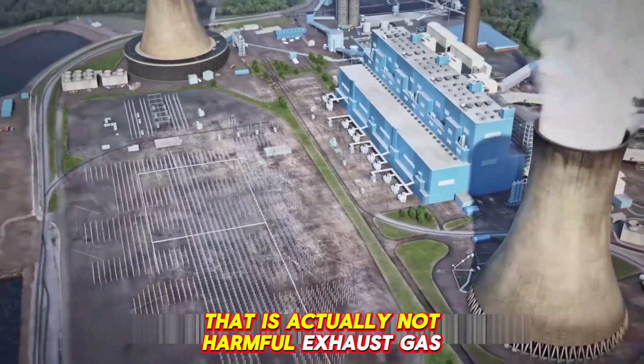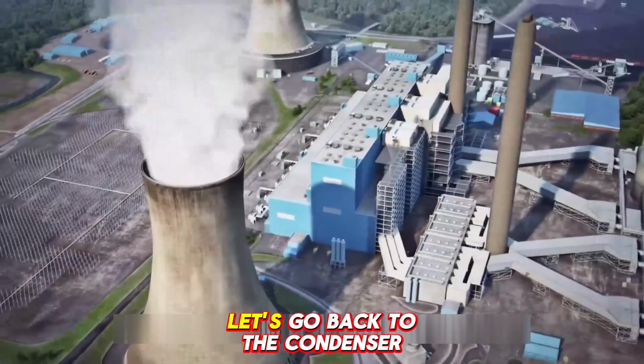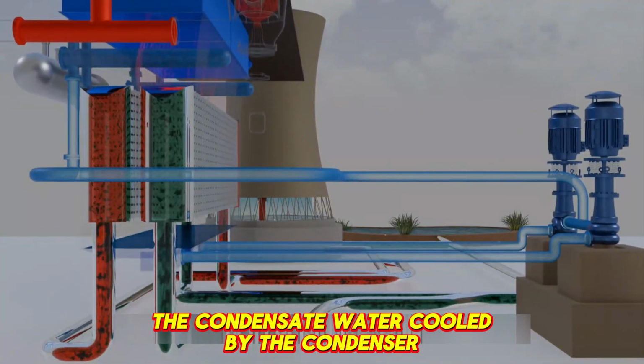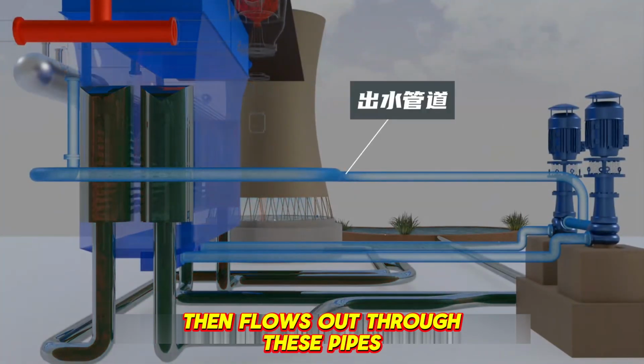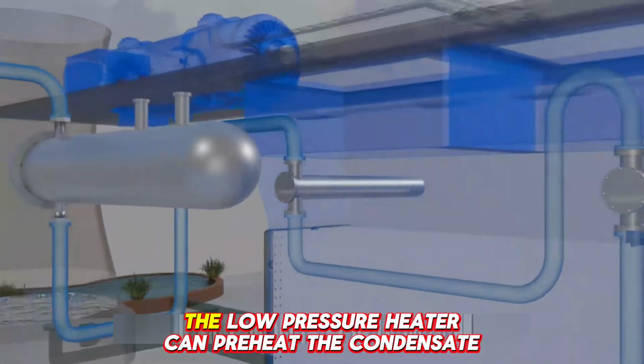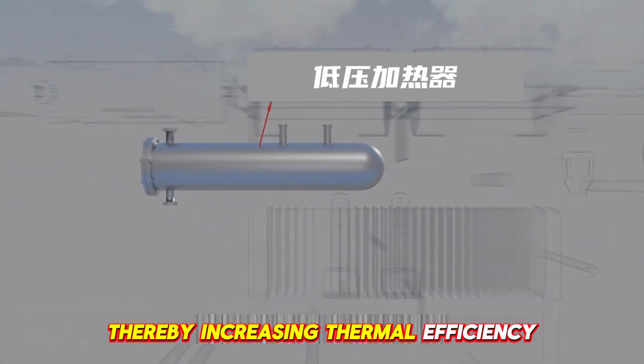That is actually not harmful exhaust gas, but rather water vapor. Let's go back to the condenser. The condensate water cooled by the condenser then flows out through these pipes. It then travels all the way up to this low-pressure heater. The low-pressure heater can preheat the condensate, thereby increasing thermal efficiency.